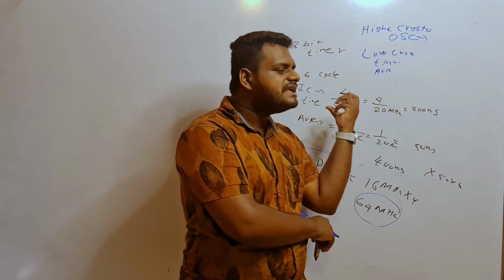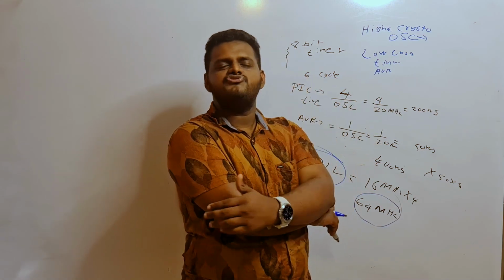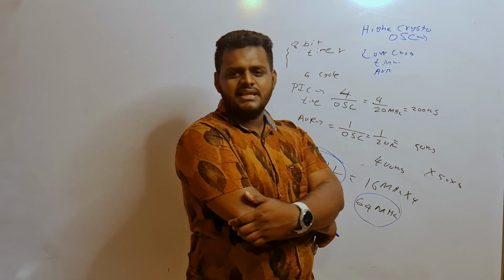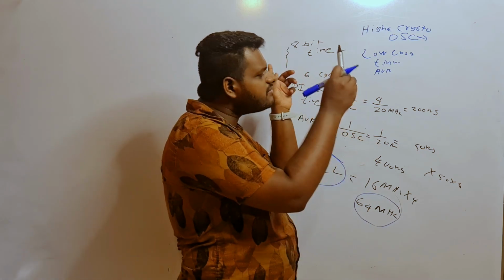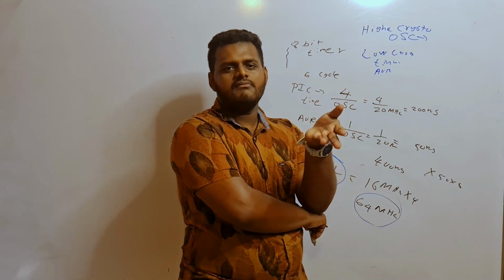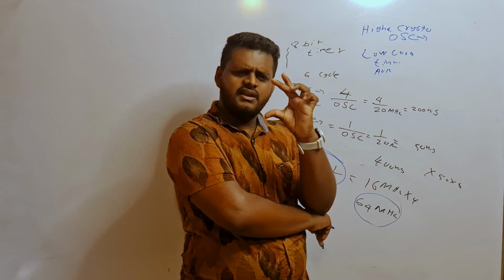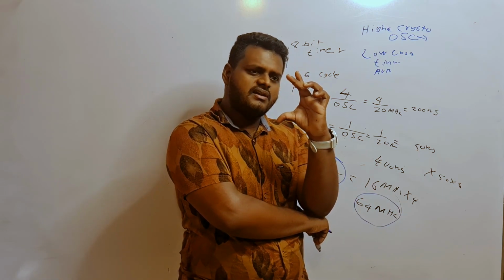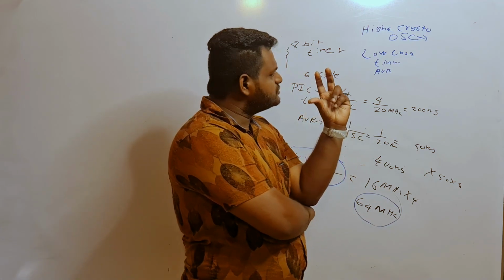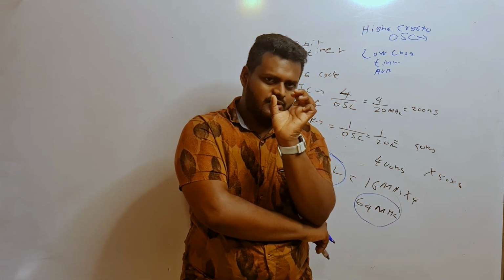So this is some sort of instruction execution timing problem. So what can I do? I think we should read the full datasheet of the WS2812, that means the NeoPixel datasheet. They clearly mention the timing diagrams for logic 1 and logic 0.